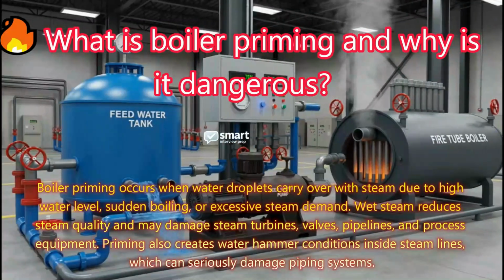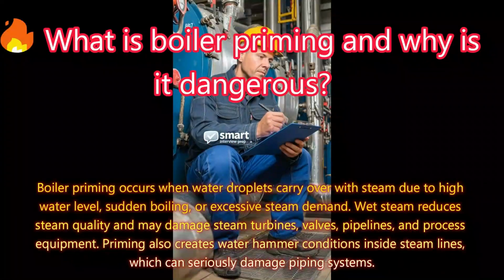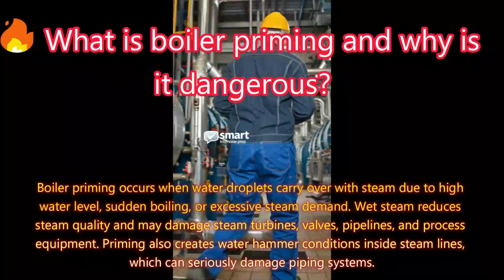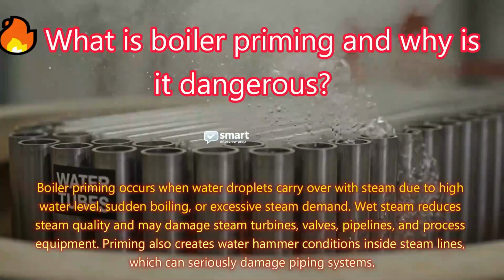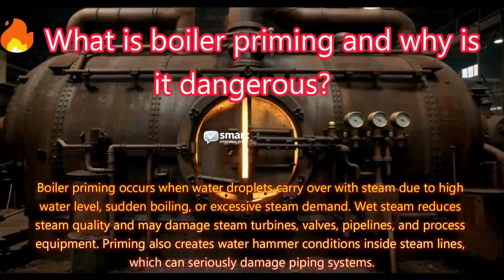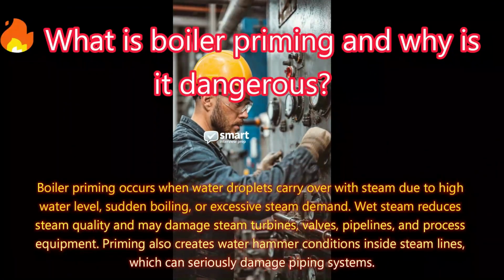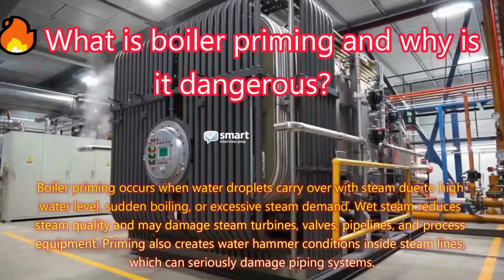Answer. Boiler priming occurs when water droplets carry over with steam due to high water level, sudden boiling, or excessive steam demand. Wet steam reduces steam quality and may damage steam turbines, valves, pipelines, and process equipment. Priming also creates water hammer conditions inside steam lines, which can seriously damage piping systems.